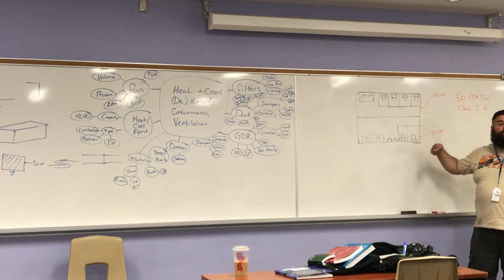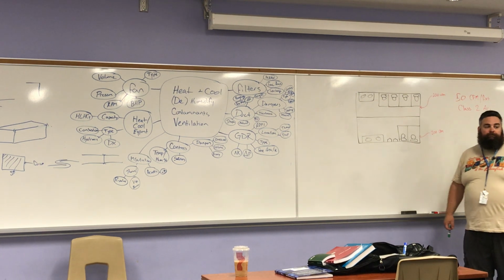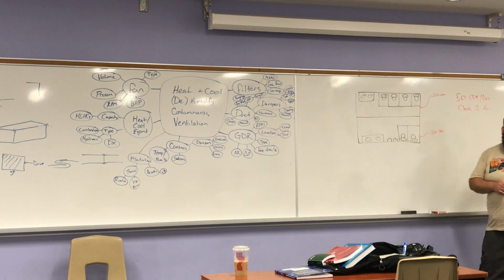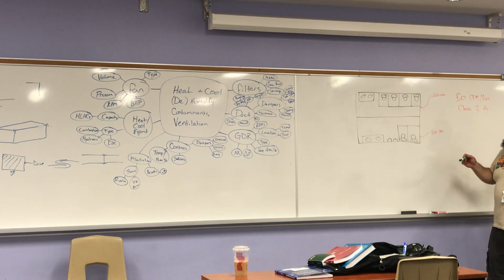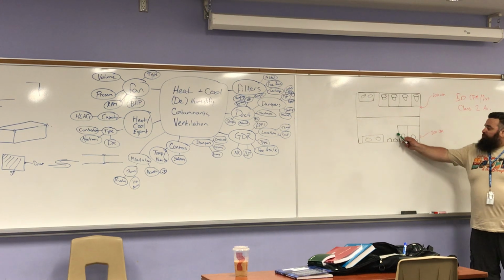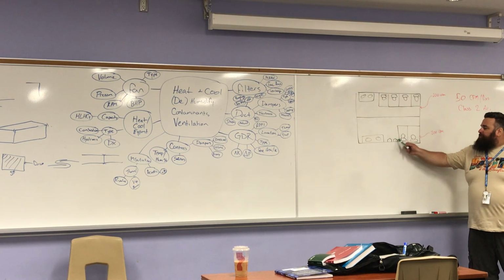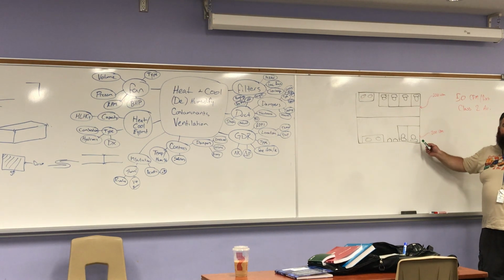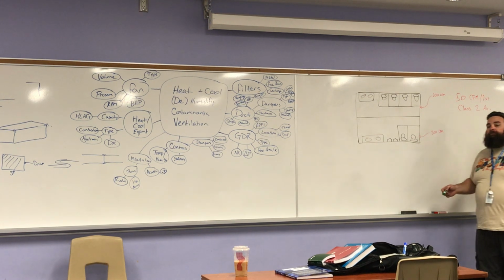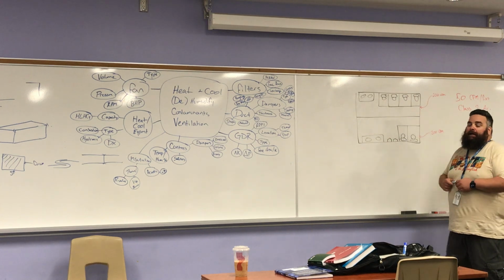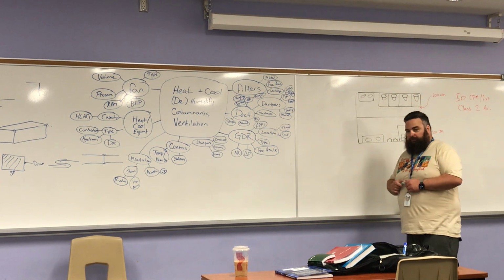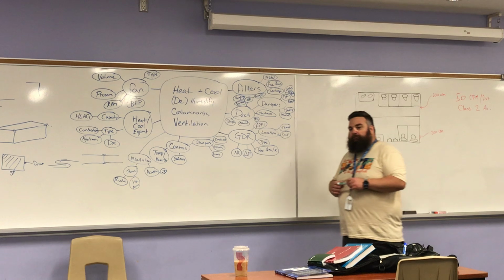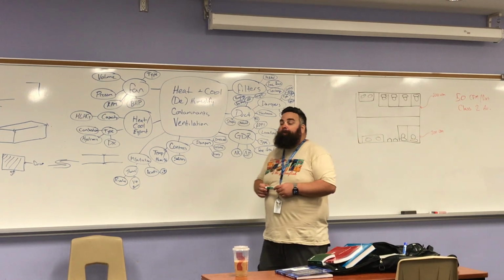What's the benefit of putting more? It's more effective. Why is it more effective? The more air gets pulled out. We're more local to our contaminant source, right? If I put one, let's say, right in the middle, it's going to capture these pretty effectively. This not so much. Okay, could you do like a long bar? You could. Same free area as like a more square shape, but just a long bar across the tops of all of them. That's an option.